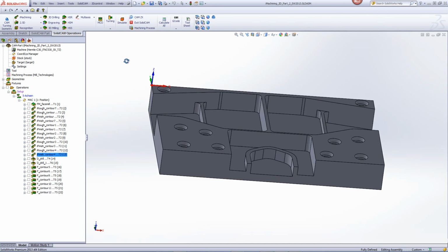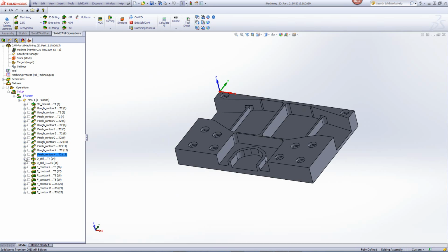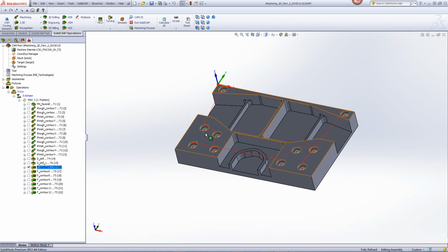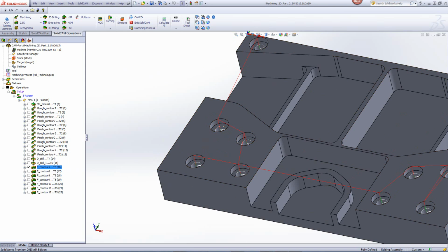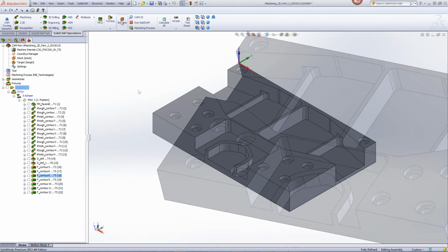The rest of the operations over here are the drilling operations needed to drill out these holes over there, and these profile operations will be doing a cut inside this hole over here to finish off the step inside over there, as well as the finish cut for those pockets. And we also have the rest of them over here doing chamfer cuts on the rest of the part.